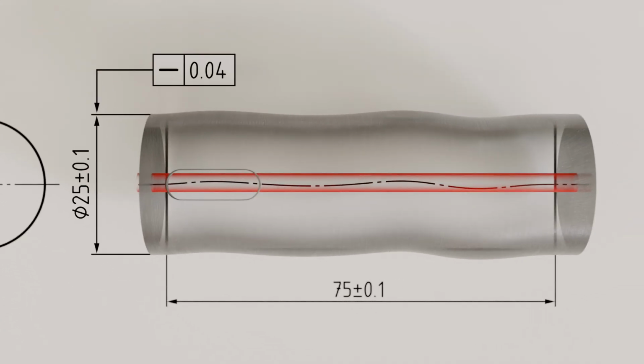However, to indicate in the drawing that straightness is no longer controlled by two parallel lines, but instead described by a cylinder with a specified diameter, the diameter symbol must be placed before the tolerance value in the feature control frame. So note, when tolerancing the straightness of a centerline, the leader arrowhead is drawn in the extension of the dimension line. If the tolerance zone for rotationally symmetric geometries is to be cylindrical, a diameter symbol must precede the form tolerance value. The centerline must then lie within a cylinder whose diameter corresponds to the specified tolerance value.